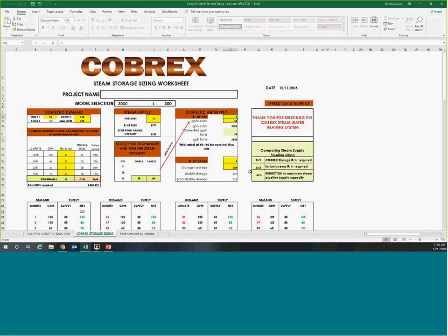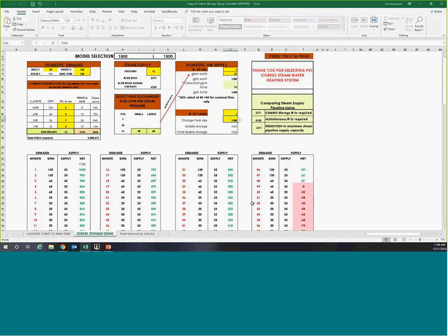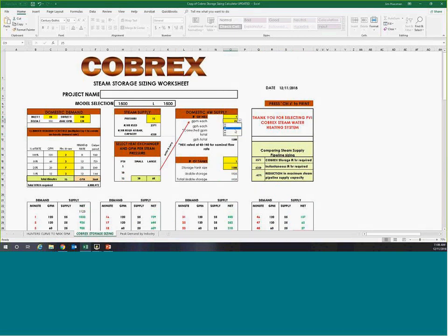If we want to switch this up, we can now adjust our design based on number of tanks and the size of the tanks, or how many heat exchangers we have, which is going to govern our recovery. So based on this scenario, let's say we want to have 1 heat exchanger at 25 gallons a minute. Since I changed that, we have 1 tank at 300 gallons. Now, if I wanted to adjust this up to a much higher storage capacity, we might be able to get away with that much smaller GPM requirement. Now, if we wanted to say we need to up this because we still can't achieve what we want to achieve.